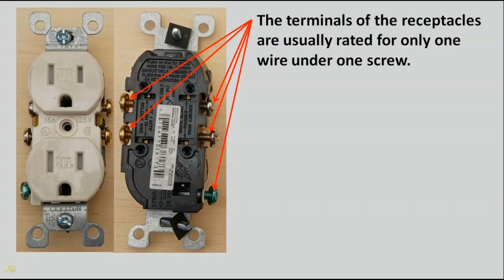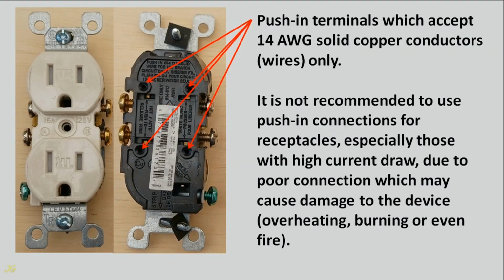The terminals of the receptacles are usually rated for only one wire under one screw. Push-in terminals accept 14-gauge solid copper conductors, wires, only. It is not recommended to use push-in connections for receptacles, especially those with high current draw, due to poor connection which may cause damage to the device, overheating, burning or even fire.